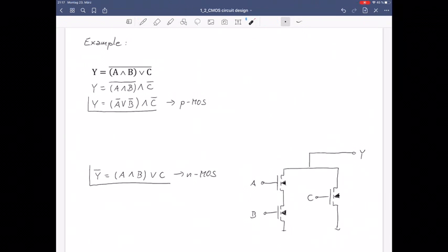Here again, I should remark that I left out drawing the wiring from the bulk contacts of the transistors to the ground. I did this just for the sake of simplicity, but in a real circuit, of course, the bulk contacts need to be connected to the ground. Now we can continue with drawing the PMOS block of the circuit.